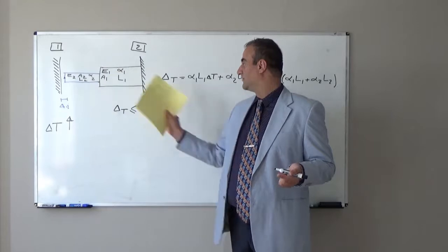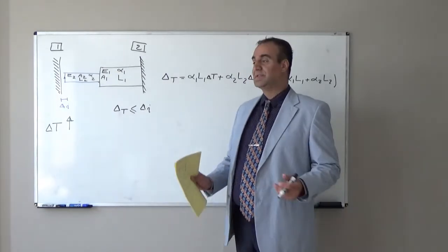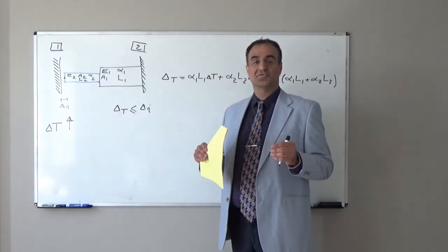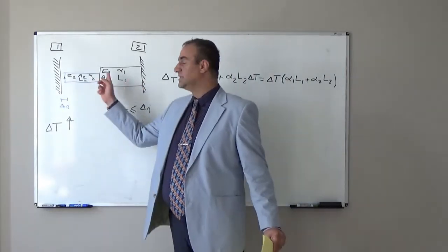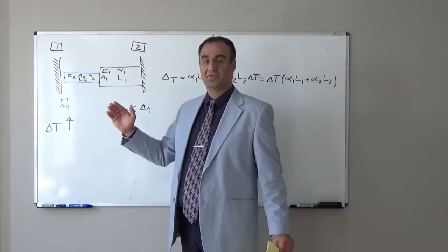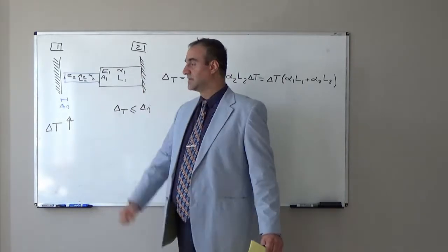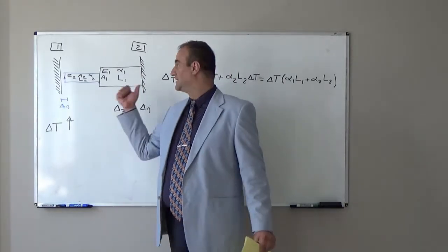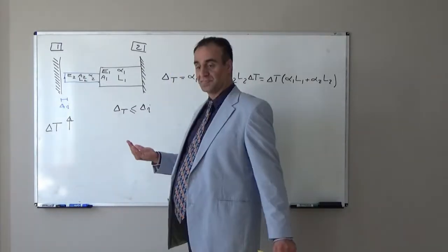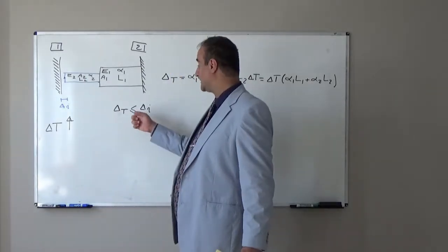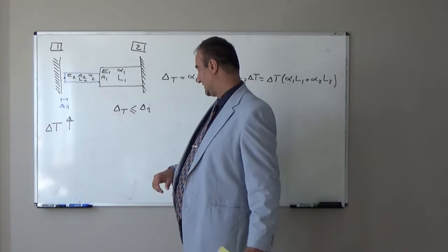We will have deformation, but we will not have any internal forces or internal stress. The internal force in each part is equal to 0. As a result, the internal stress is equal to 0 and the axial reaction will be 0 too, if it is smaller than or equal to the initial gap.